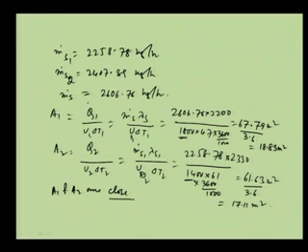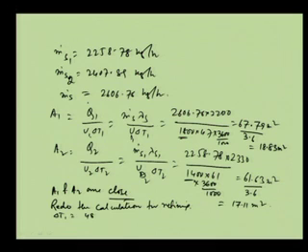So, for that what we have to do? We have to redo the calculation for refining or improvement. Then delta T1 we will take as say 48 degree centigrade, and delta T2 we will take say 60 degree centigrade, and redo till A1 is nearly equal to A2. So, this is the thing that is being done in case of evaporation calculations.